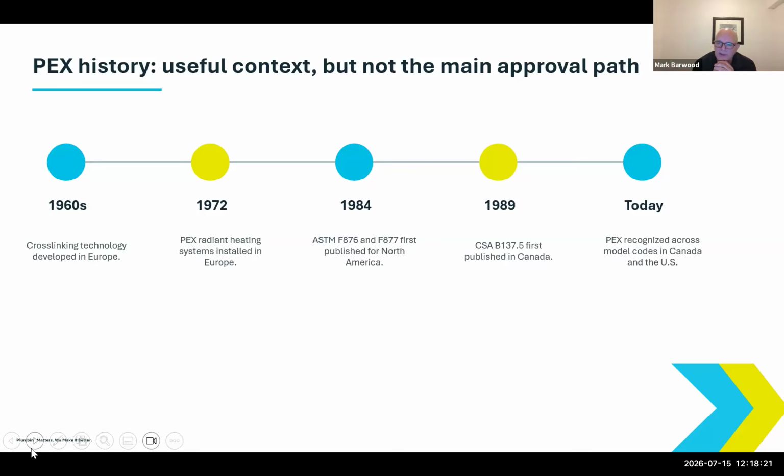I always joke with new housing plumbers, and I say, when last did you see a house plumbed in copper? And they reckon, if you want to build a custom house and you want it plumbed in copper, you're going to pay a significant extra amount of money for that, because they say, we don't even know if we can still do a house in copper. We may not even have the skill set to do that, because these guys just run PEX. All the high rise buildings now, in the suites, everything's PEX. It's so much easier to work with, and it's faster and more cost effective.